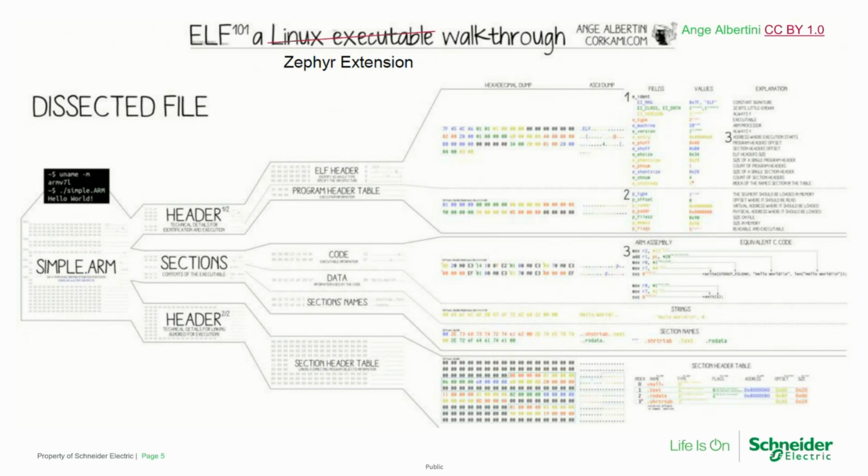Basically, you have your .data, your .bss, your .init, .noinit, stuff like that. And then you have different headers because your section can be split into two other sections. You can do everything you want with this system. That's what Zephyr uses for the base firmware, but it uses the same for the LLEXT feature.